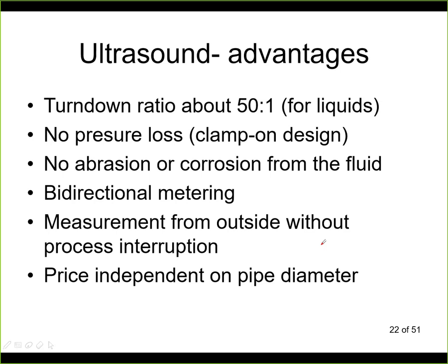This is the before last point. That's for the clamp-on system. It can be measured without interrupting the process, and if you have the clamp-on system, the price is virtually independent of pipe diameter. You still have the same sensor, you just have a different fixture where you fix it on the wall.